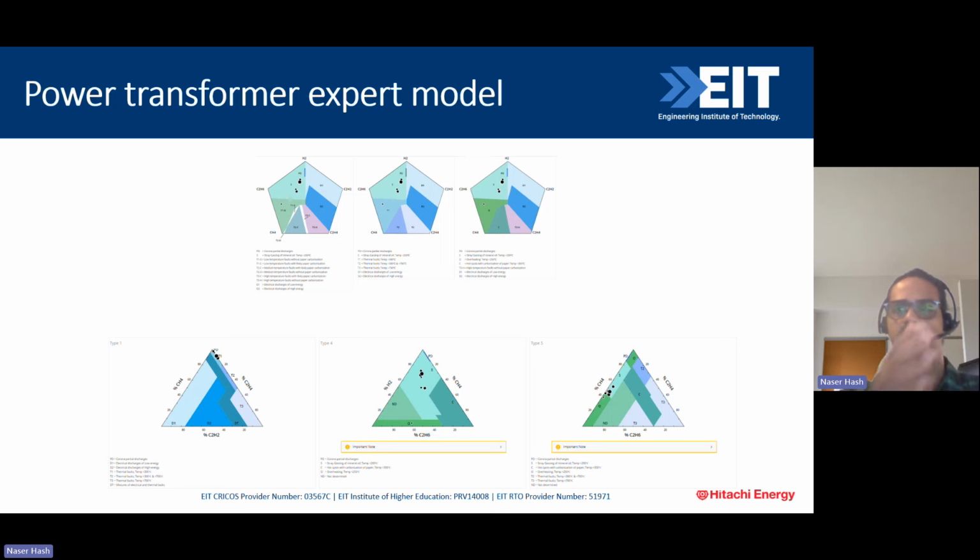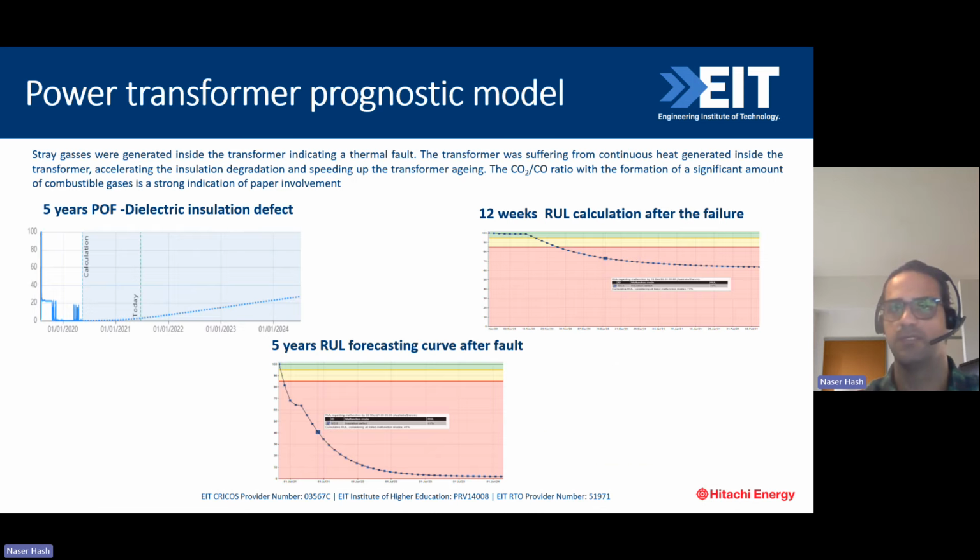If that DEM problem is calculated every day, it becomes an input to the model, and based on some percentage calculations on derivative parameters that we apply as input to the model, we can find out whether the severity of this DEM problem is going to go to the next level or not, and when we need to do a shutdown and take the transformer out. So that's another beauty of the solution, that it can predict the insulation degradation.